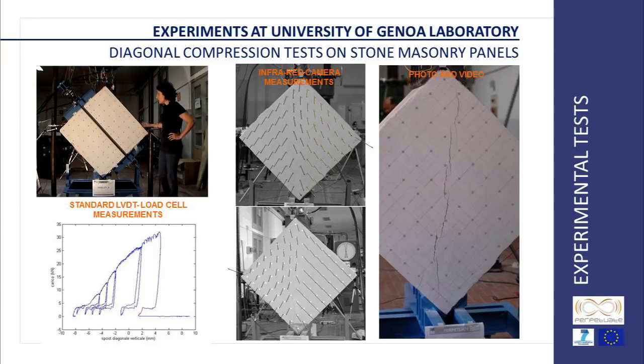We measure the displacements on the panels by means of markers, which are analyzed by an infrared camera, able to trace the displacement of each point in the test.